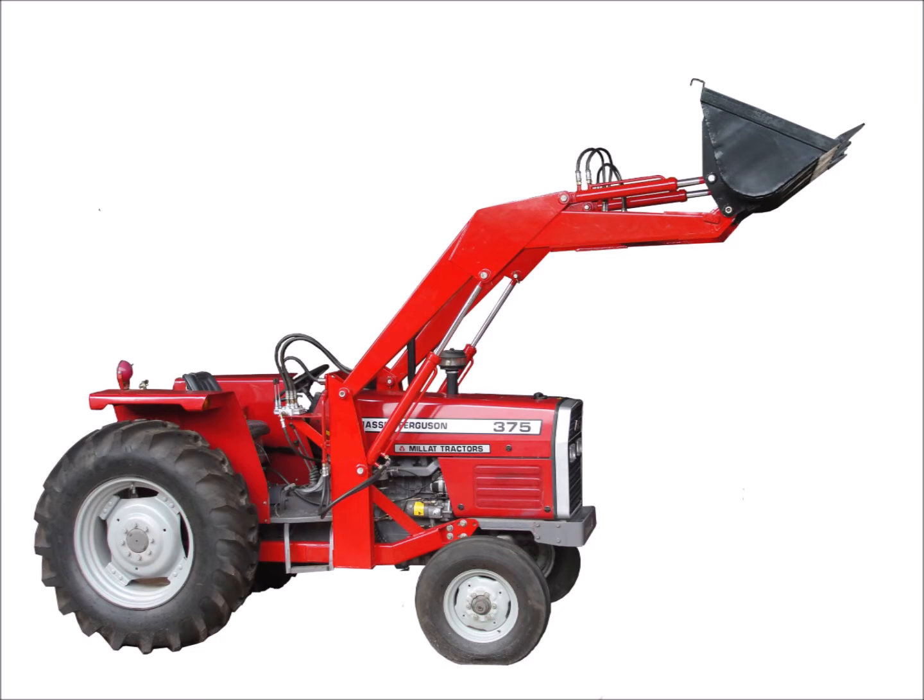And these will push the loader up, and then the other ones will tip the loader. You can see whether the arms are double acting because they'll have valves, or piping, on both ends. This would allow it to exert force, either pushing or pulling, depending on what you've selected.